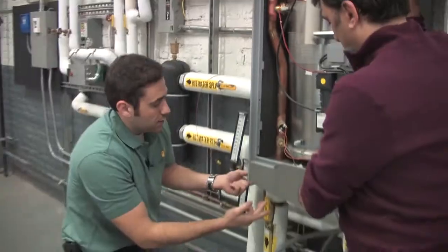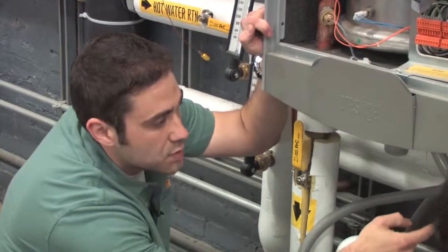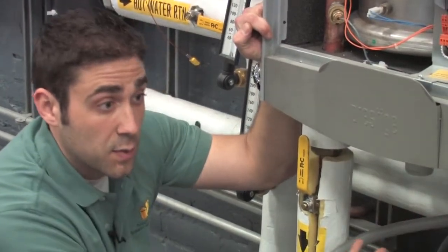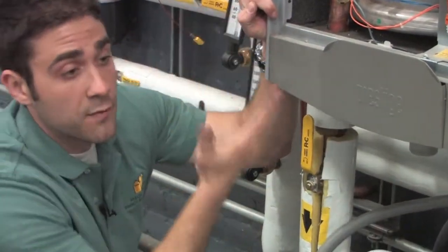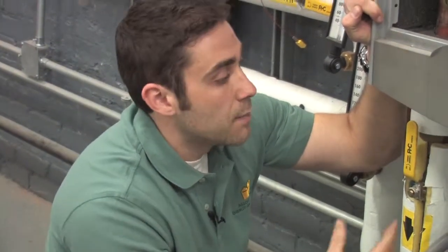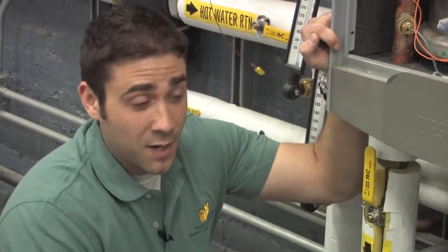If you take a look down here, we can see this little trap at the bottom. So the condensation collects inside this little trap, works its way up, and then goes through our drain pipe into a little condensate neutralizer kit. This condensate is acidic, like we talked about before, so we have to have the proper venting. It needs to be PVC or stainless steel, something that won't corrode. Being that it's acidic, we can't just dump it into the drains. You know, in New York City here, we have a lot of cast iron. So if we do dump it into the drains, we'll start to rot out that cast iron.